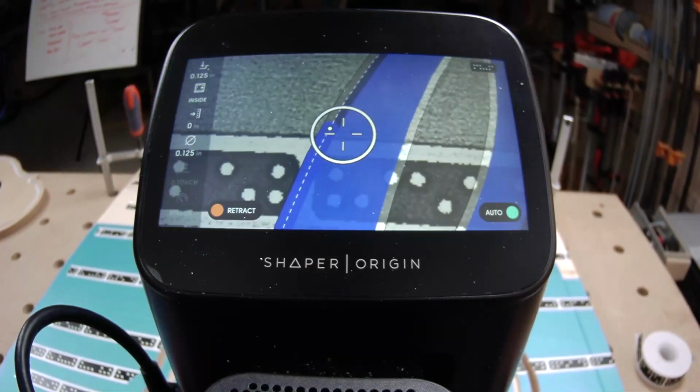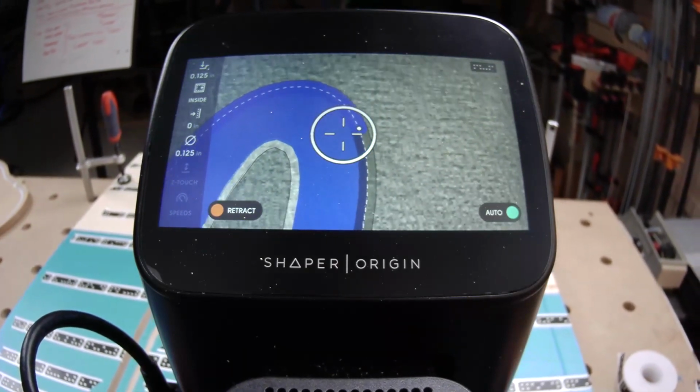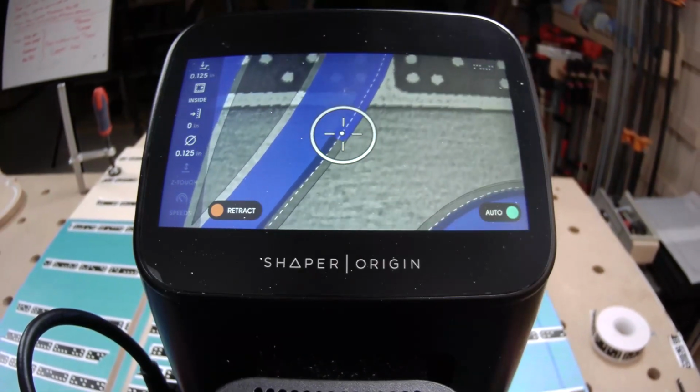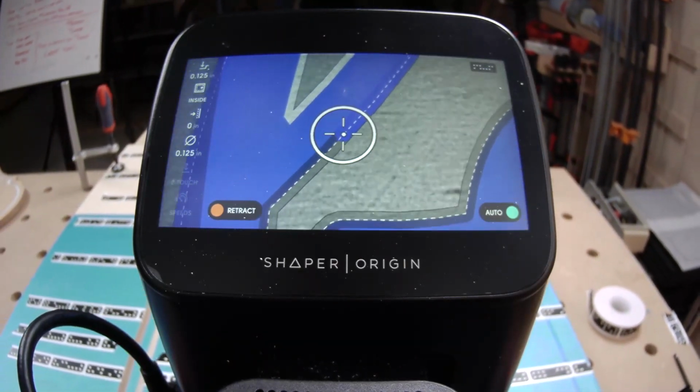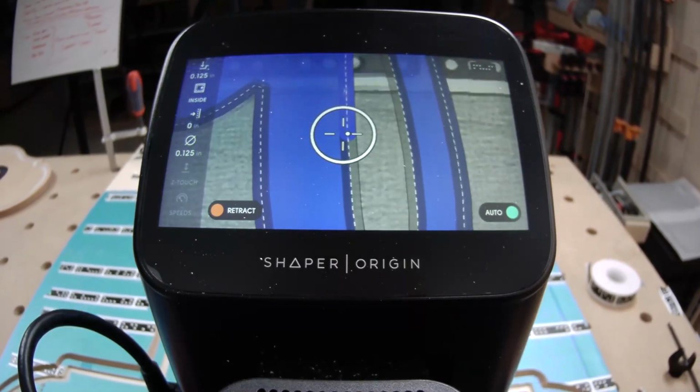Also remember, if you're using epoxy to fill big volumes in wood, that different epoxies are set for curing at different thicknesses. So, there will be really quick cure epoxies that could work for very shallow depths.